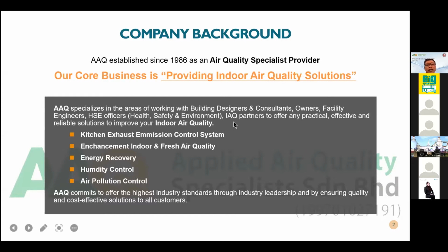And then we enhance indoor air quality with a fresh air energy recovery ventilator, which Encik Mazlan did mention to me to help assist. Energy recovery or heat recovery ventilation is not recommended by DOSH because it may cause cross-air contamination and also some humidity issues.